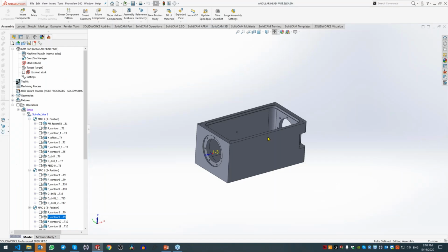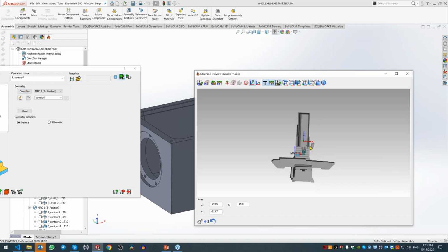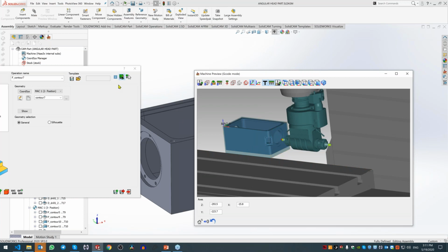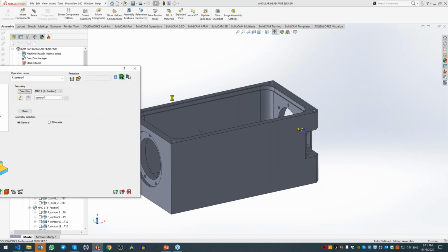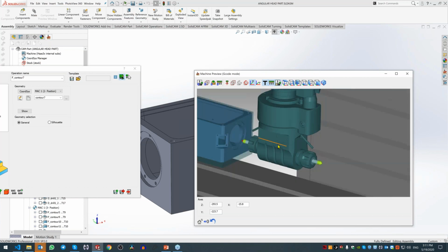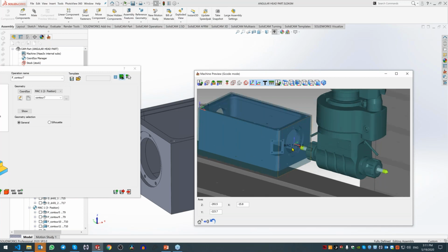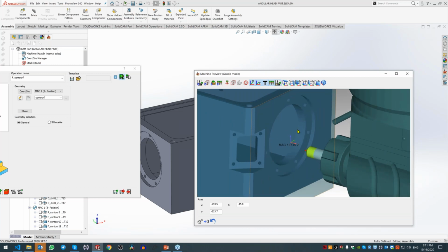So we will go back again to this part, and we will start from the operations on the right side. On this right side, let's open some profile. Yeah, it was a profile with ARC. In this operation, I just want to interpolate this chamfer for this feature with an ARC. In general, my machine does not support plane rotation, so my coordinate system for position 2 will not rotate. So my arc will be executed in the ZY plane.